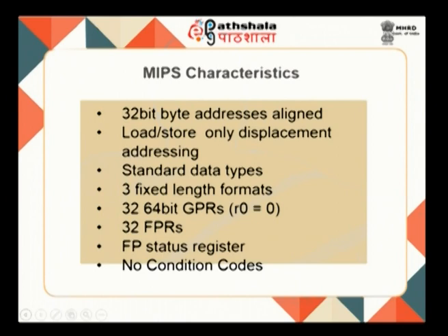The basic characteristic of the MIPS architecture is that it is basically a RISC architecture. It follows a load store ISA, which is a register ISA. It is called a register ISA because the operations can operate only on register operands. I can have an instruction like add R1, R2, R3. So, all arithmetic or logical operations have to be done only on registers, and in order to bring information from memory or write information onto memory, you have what are called load and store instructions. Load and store are the only instructions which allow you to have memory operands.